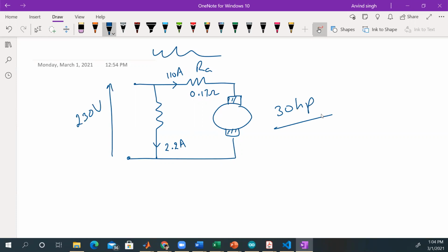Now this output of 30 horsepower represents the power available to the user. So this is after all the losses and everything. This is the amount of power available to the user. And that's a very important thing, because when you buy a motor, you don't want to select a motor based on some internal parameter, and you don't actually know what you're going to get out after the losses and so on. You'll have to do this for your final project as well.